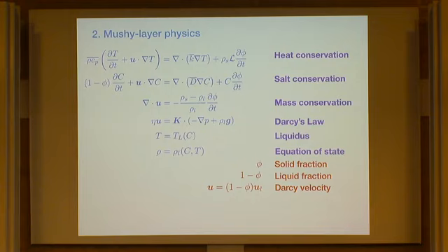So that means that in terms of the structure of this system, this second equation, which looks like an equation for C, is really an equation for phi, because T is controlled to a large extent by the first equation. It's a coupled system, but you can understand the real physics by thinking of this as an equation for the temperature, and this as an equation for the solid fraction, and they're coupled by the second one telling you how much latent heat is released as the thing solidifies.